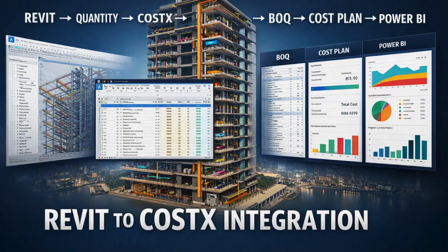This practical learning module on Revit to CostX integration. In this session, we will learn how to take BIM model information from Revit, convert it into reliable quantities, transfer the information into CostX, develop a BOQ and cost plans, and finally prepare the data for project cost analysis and Power BI reporting. This is not a software demonstration. The objective is to establish a controlled BIM to cost workflow.